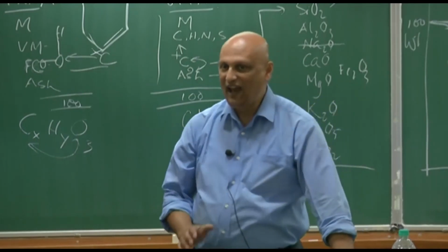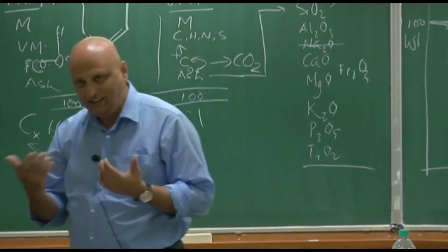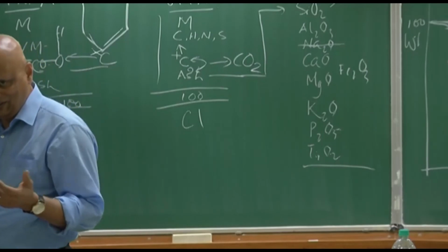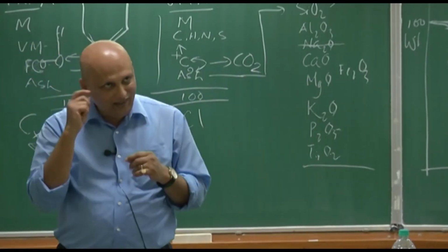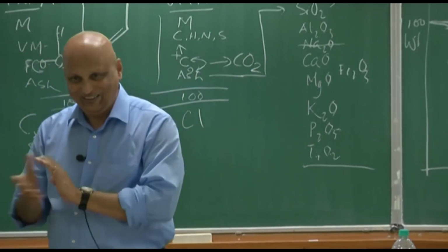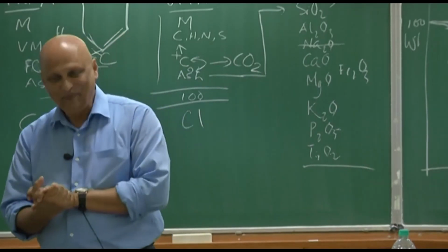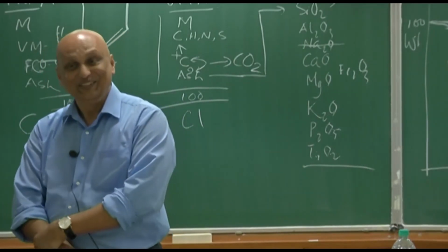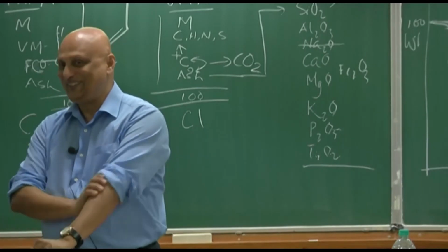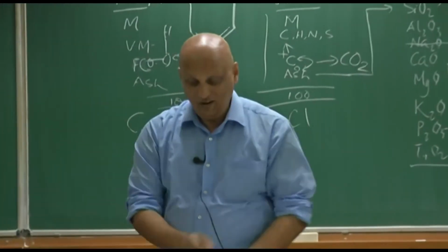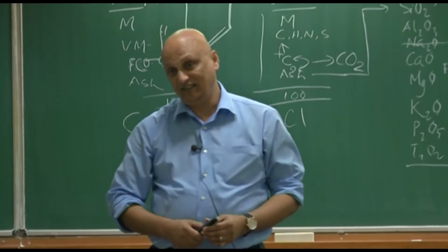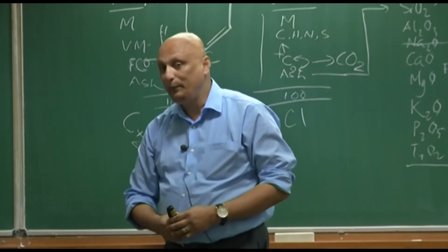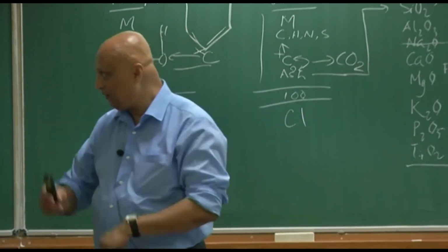So we are talking about the ash viscosity. Ash is like any other compound. In viscosity, we typically align ourselves to water, a liquid, right? But in real life, ash also can have viscosity. We measure ash viscosity at 1600 degrees centigrade. It's a big challenge. We'll talk about that later on.